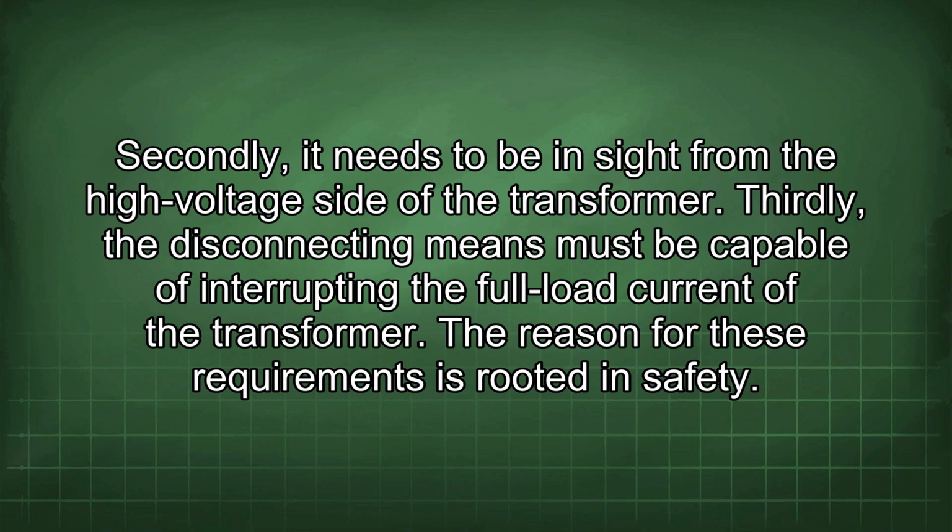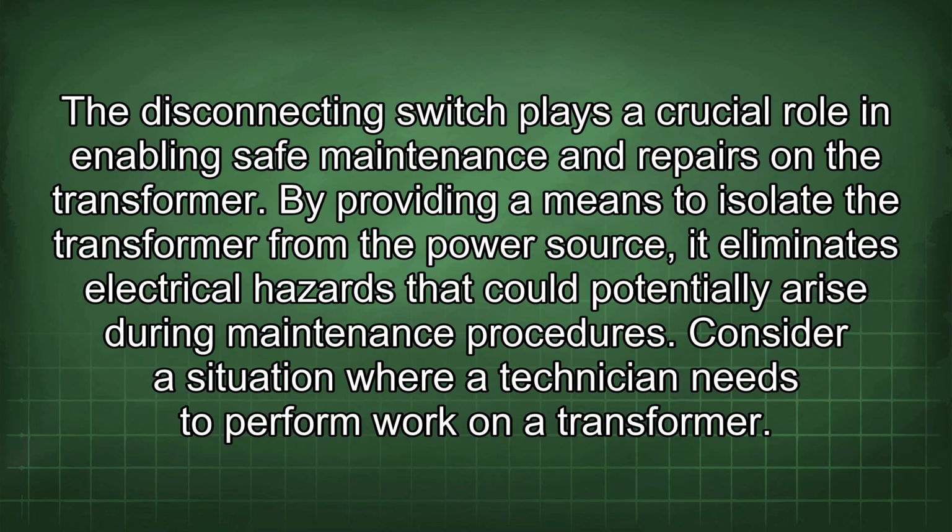The reason for these requirements is rooted in safety. The disconnecting switch plays a crucial role in enabling safe maintenance and repairs in the transformer. By providing a means to isolate the transformer from the power source, it eliminates electrical hazards that could potentially arise during maintenance procedures. Consider a situation where a technician needs to perform work on a transformer.